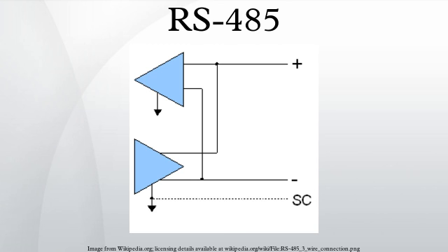This section also defines the logic states 1 and 0, by the polarity between A and B terminals. If A is negative with respect to B, the state is binary 1. The reversed polarity is binary 0. The standard does not assign any logic function to the two states.